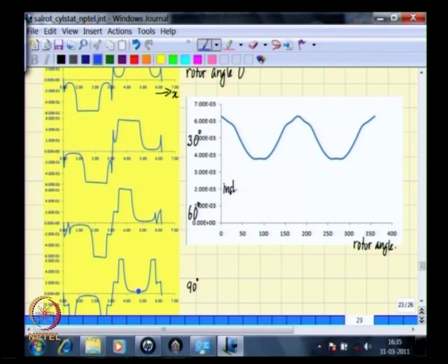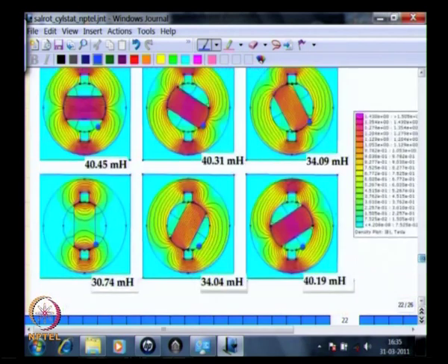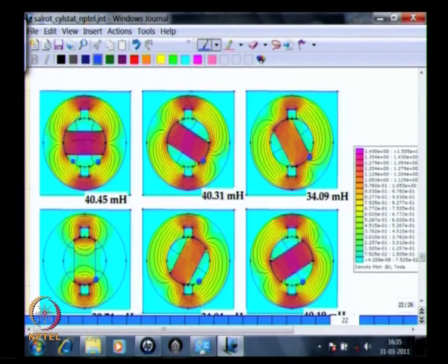Interpolar region, low flux density. Wherever there is the rotor pole face, you have high flux densities. Where the interpolar area or the face of the rotor pole occurs will depend upon the rotor angle. So, as the rotor rotates, now the interpolar region is here in this area, but this area will now slowly contain the pole face. Here it has the pole face fully, and as the rotor rotates, this area becomes interpolar region again.